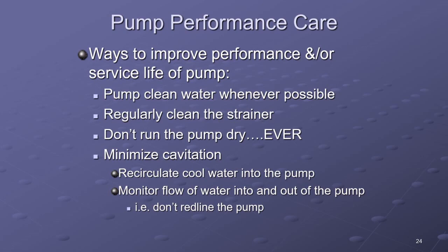So take care of your pump. If at all possible, pump clean water. I mean, when you run dirt and stuff in there, you get scouring, you get wear on your equipment. Clean your strainer, because a clogged strainer makes your pump work harder. It's harder for it to pull the water in. Don't run the pump dry, ever.